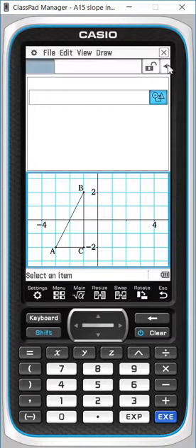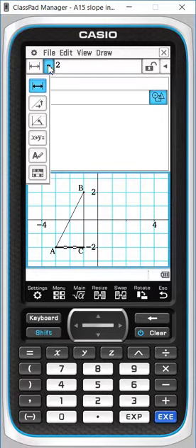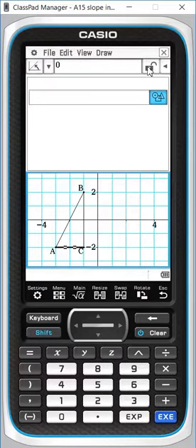So now I want to insist that that is going to remain horizontal. So I'm going to choose this one here, set it to 0, that's the angle I want, so it stays horizontal. And we do that, tap an open space, choose side BC, fix that to 90. It's already 90, that's good. Tap an open space, and we've now selected them. To demonstrate how it happens, now we should be able to move this point, and we remain having that triangle with AC horizontal and BC vertical.